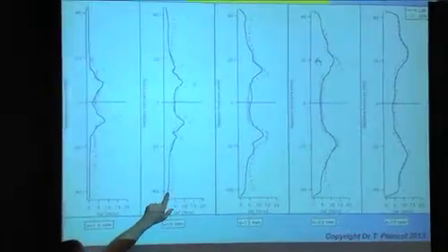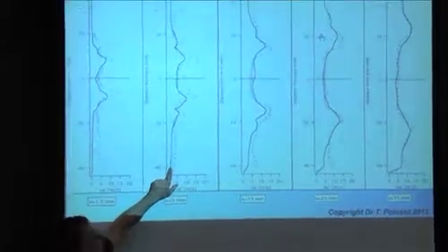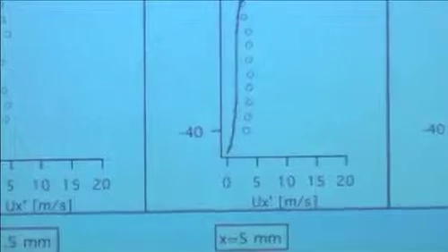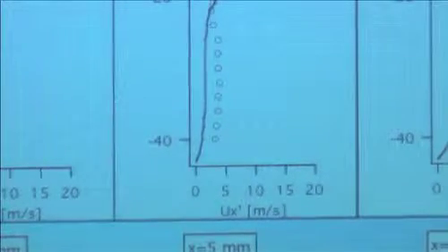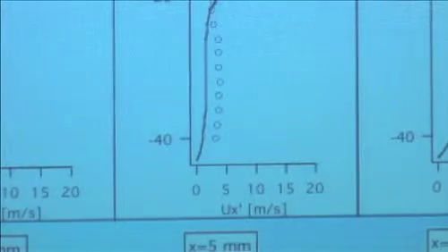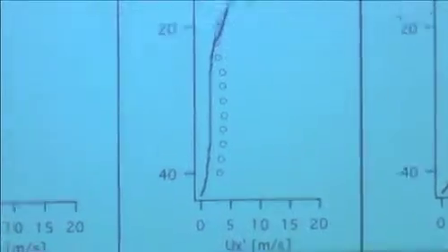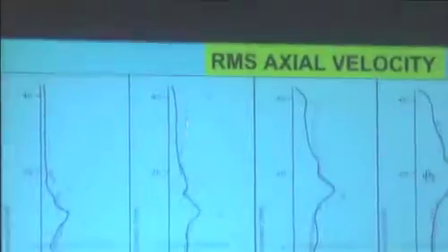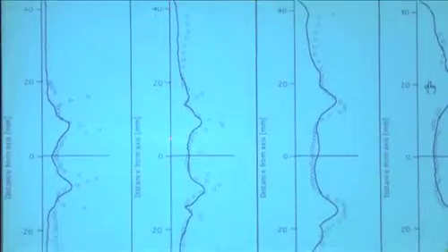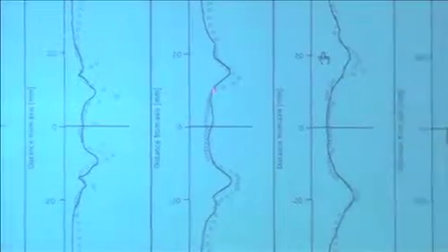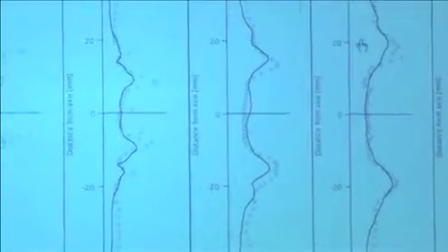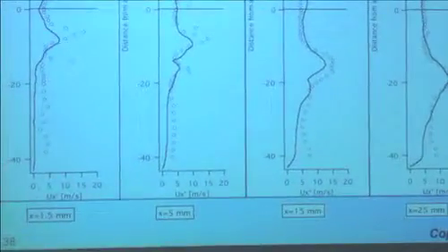Between the two, this one has to be always smaller than that one, because from here to there is the unresolved subgrid scale variance that has to be added. So you can also say that in places like this, there are very few. Normally, this LES curve should always be less than that one, okay? Otherwise, there is a problem. In most cases, it is. You see it's below, except a few points here. But otherwise, the agreement between the two is still very good.